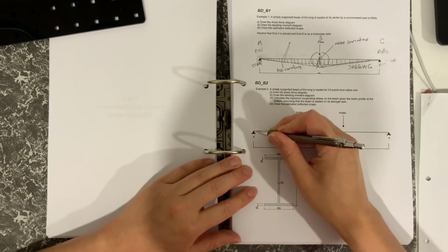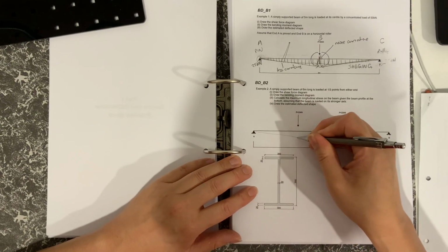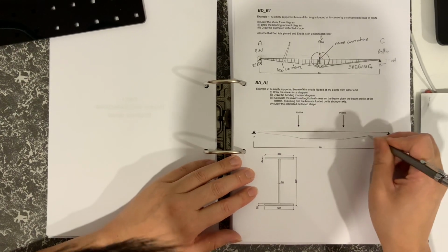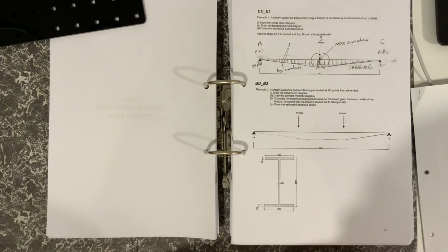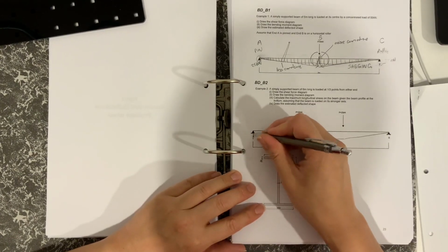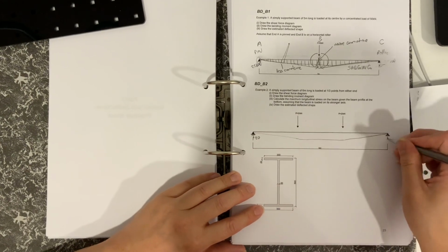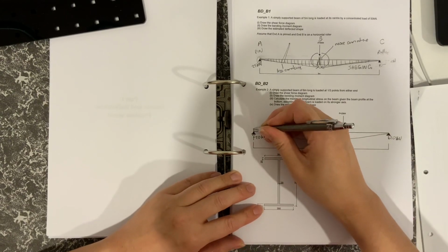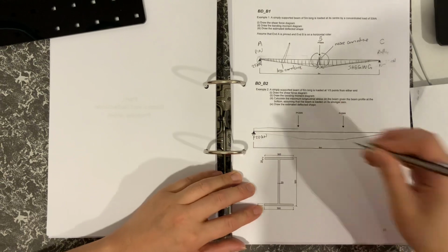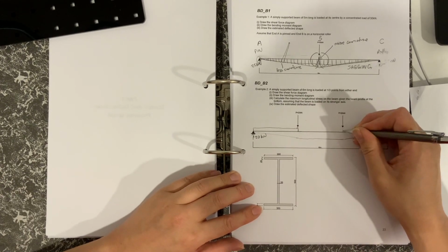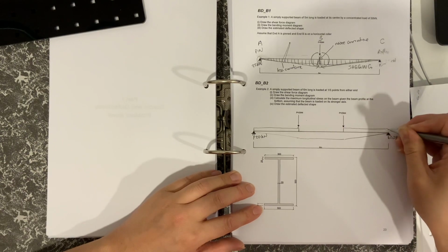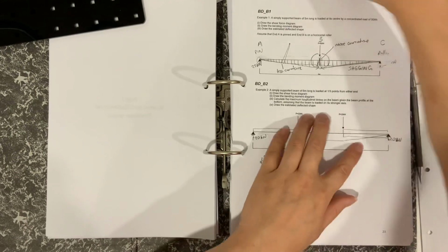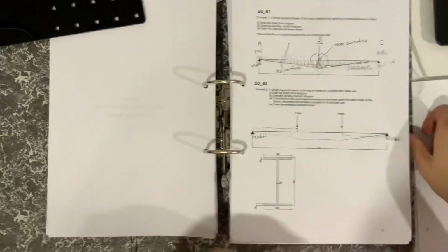So in this one here, the bending moment diagram would go down like that, and then after that it would be constant over there, and then it would be going up like there. Okay, so that would be the bending moment diagram. The reactions there would be 20 kilonewtons upwards at each end. So the shear force diagram would go 20, drop down to 0, and then go back up here. So that would be the shear force diagram. If you can't quite make out what I'm doing here, just look at the solutions.